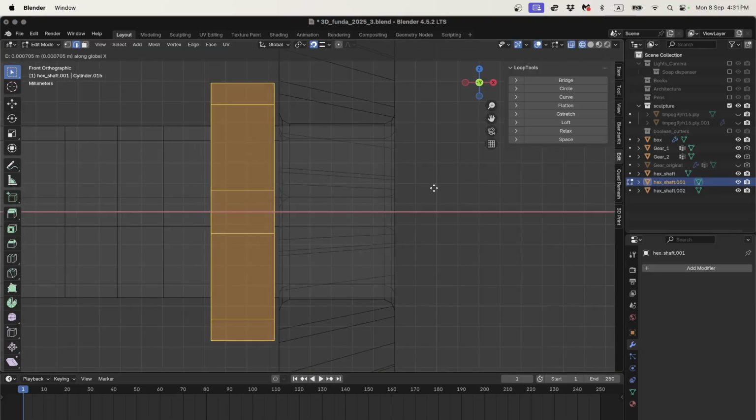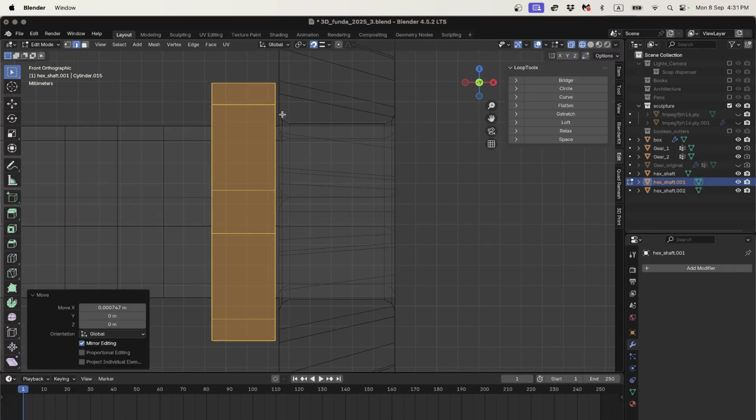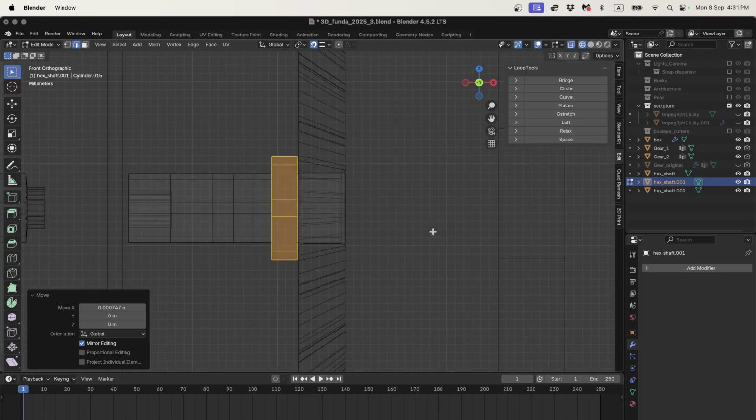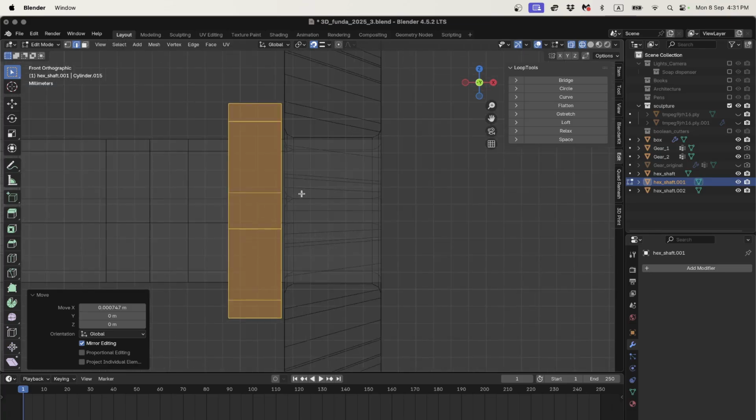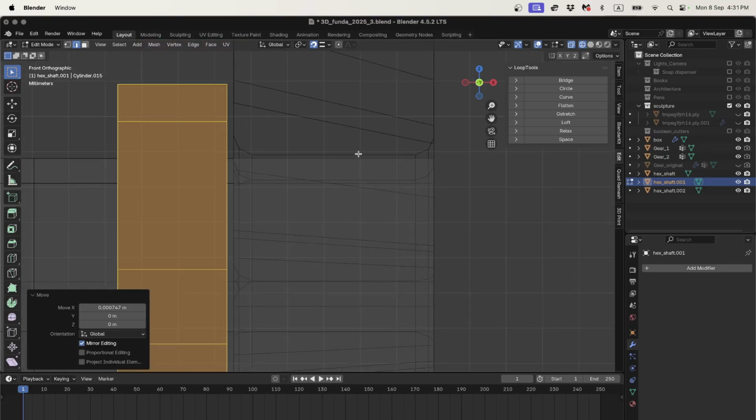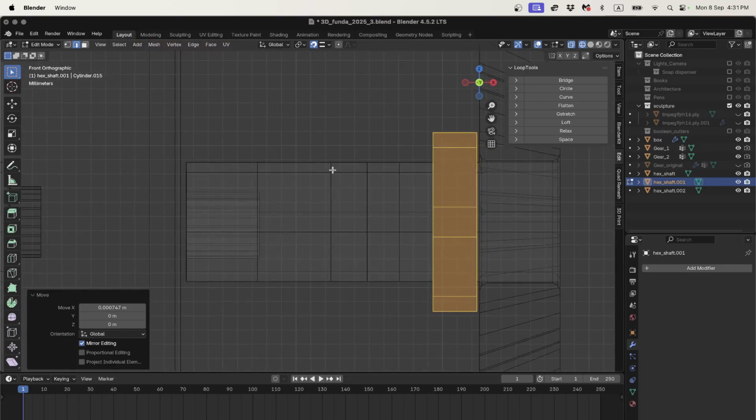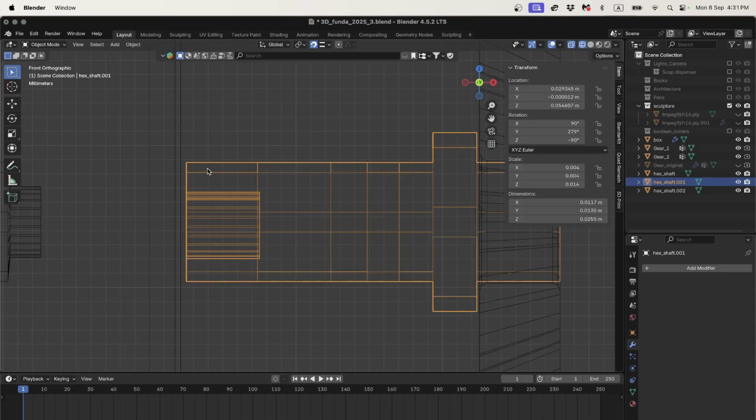and I'm just going to eyeball this. I don't want everything to be too precise here because it's the physical world. I want to leave some little gaps of less than a millimeter here and there. If we're prototyping something really exactly, we might get this even more precise. But we're working here with plastic, so the plastic has a tiny bit of flexibility, and it's also the first time I've tried this. So I'm making a few guesses, leaving these little gaps, like we did with the hole versus the hex shaft and so on.